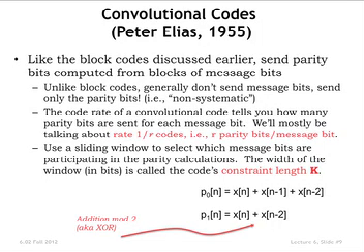So convolutional codes. And again, I keep coming back to MIT names. Peter Elias was on our faculty here. He was a department head for a while. And in a short paper in 1955, invented the idea of convolutional codes. So the idea here is not to divide up your data into blocks, but to actually work on the streaming data. And as the data goes past, you generate parity bits at a regular rate. And what you transmit in most typical schemes are just the parity bits. You don't send the message bits. So this would be a non-systematic code, if you like. So there's no part of that message that's directly observing the message bits.